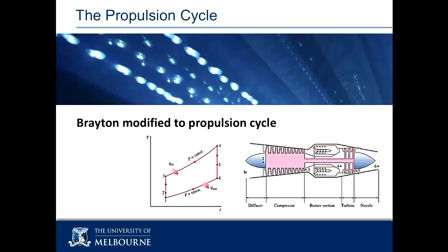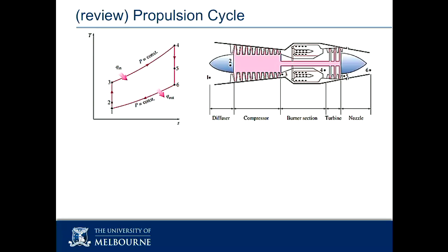If you want to find out the temperatures at point 1 and point 2, you're using the air standard T2 on T1 equals P2 on P1, gamma to the minus 1 on gamma. I say that like it's natural that you would have memorized it by now. This is an equation you will be given on your equation sheet. You need to recognize it and know when to use it. So let's have a look at those different components.